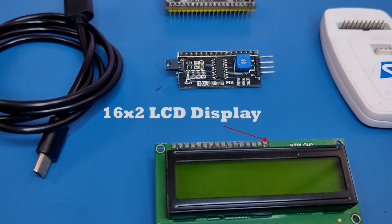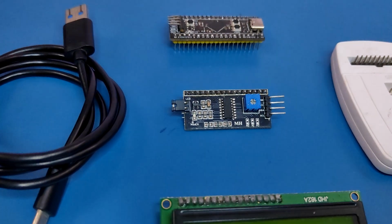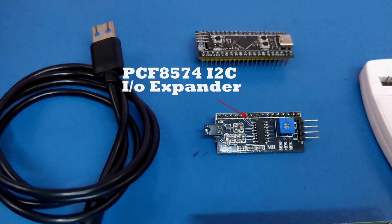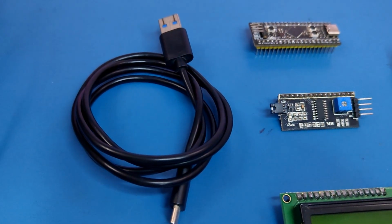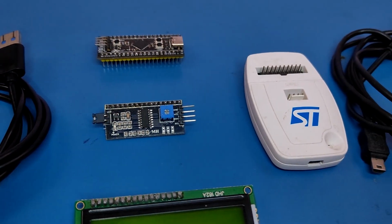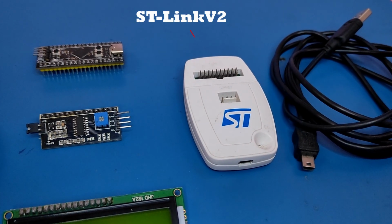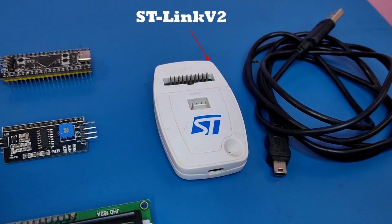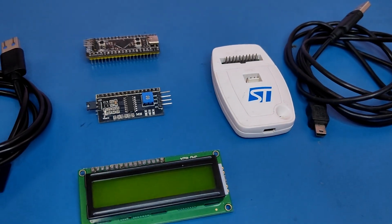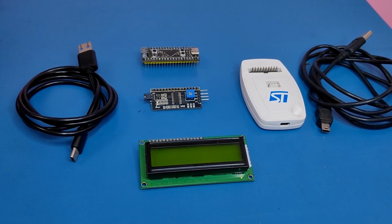Here's the component lineup: a 16x2 LCD display, a PCF8574 I2C IO expander module, an STM32 F411 based Black Pill board, a USB-C cable for power, and finally an ST-Link V2 programmer for flashing and debugging. The ST-Link V2 uses a USB mini connector, so make sure you have the right cable.